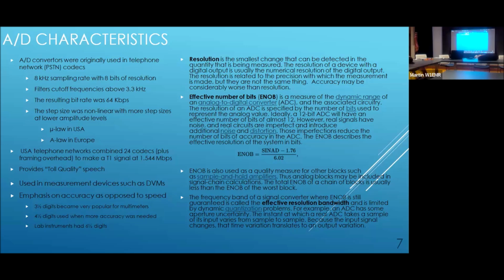So for a hybrid circuit, using something behind that mixer, there's going to be more variables in that particular receiver, thus making it more difficult to measure stuff than it would be if that A to D converter was directly connected to a filter and your antenna. Okay.